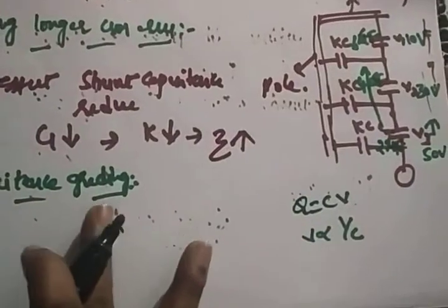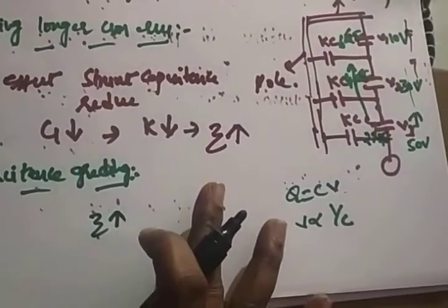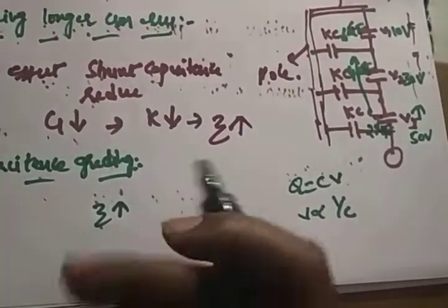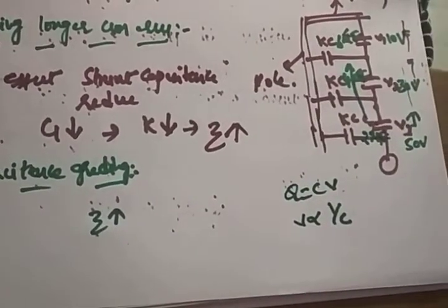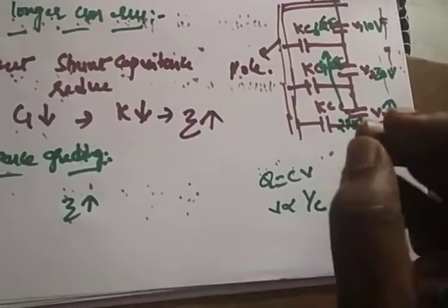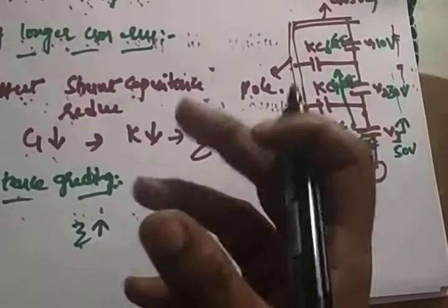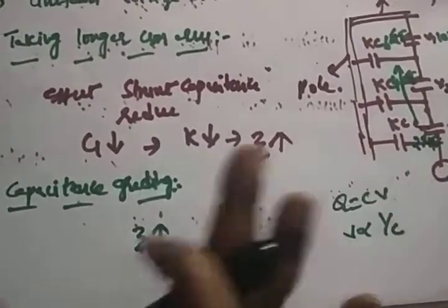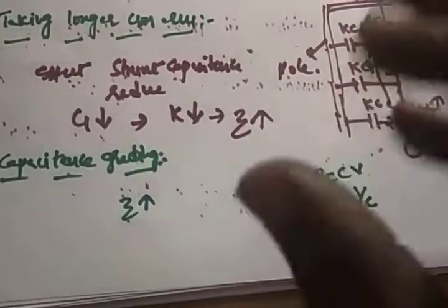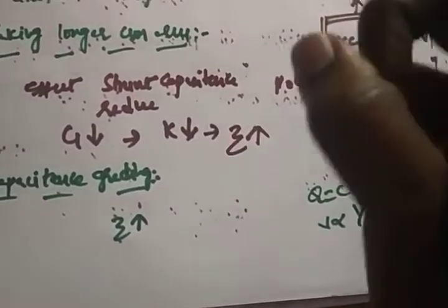But one drawback is that each and every time you have to take different values of capacitance. It's not practical, right? The disc nearer to the conductor has less capacitance, so there are easy chances of failure of that capacitance value. So that is a disadvantage. It's very difficult to maintain in a string. Each and every disc is a different type.